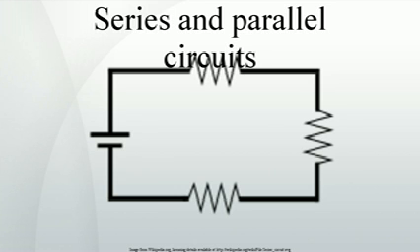Resistors. The current in each individual resistor is found by Ohm's law. Factoring out the voltage gives the following. To find the total resistance of all components, add the reciprocals of the resistances of each component and take the reciprocal of the sum. Total resistance will always be less than the value of the smallest resistance. For only two resistors, the unreciprocated expression is reasonably simple. This sometimes goes by the mnemonic product over sum.